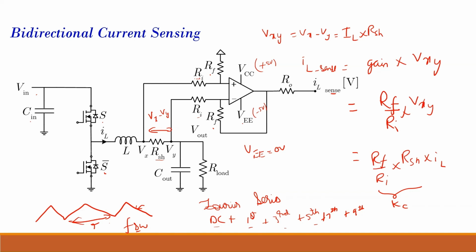So for this to happen, you must make sure that the bandwidth of your op-amp is greater than 10 times your switching frequency.